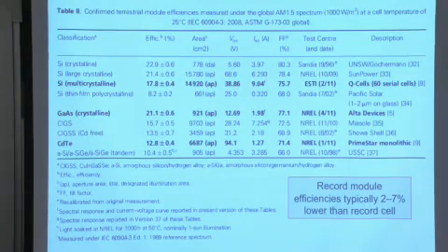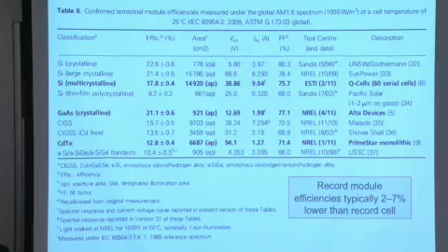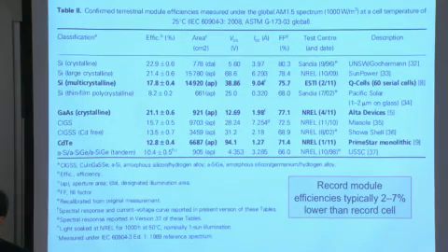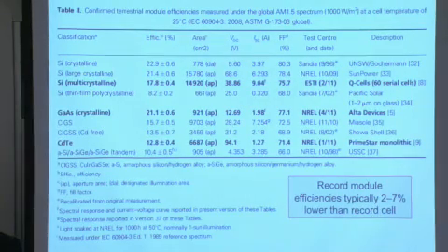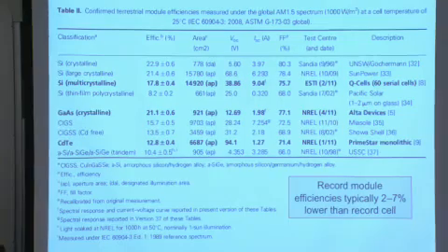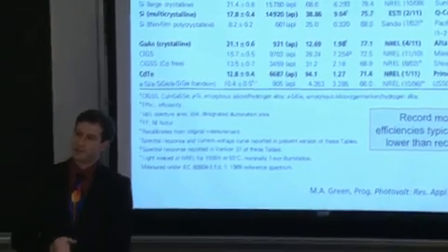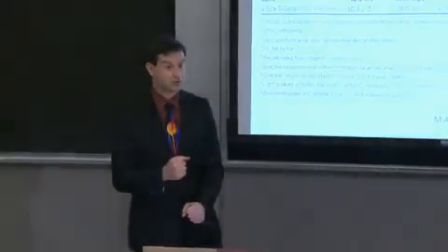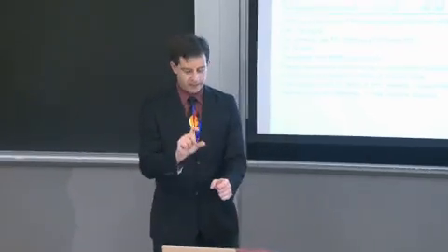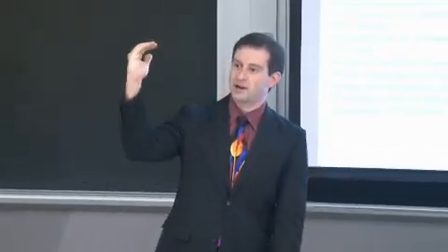Inhomogeneities, exactly. So if you have inhomogeneities in thickness or in composition or even in surface quality from region to region in that large area, you're likely to reduce your performance. One analogy, since I know many of you are mechanical engineers, is when you're doing tensile tests with ceramics or brittle specimens at room temperature. You pull on your specimen and you obtain a certain fracture stress. You then take that smaller piece, pull again. Now the fracture stress is higher. Pull on that smaller piece that broke off, yet again, and now the fracture stress is even higher.